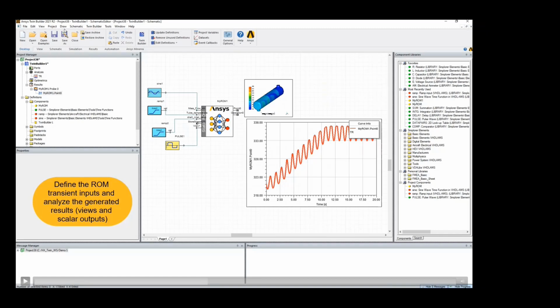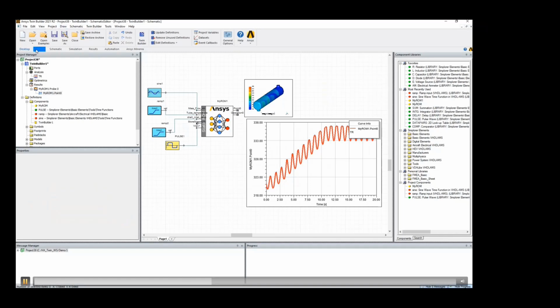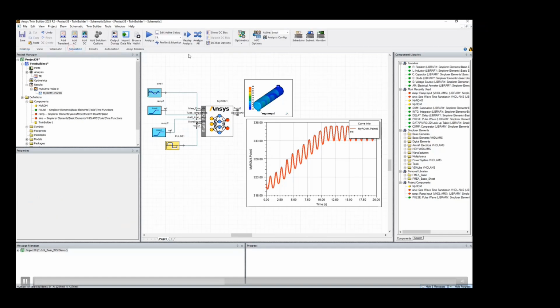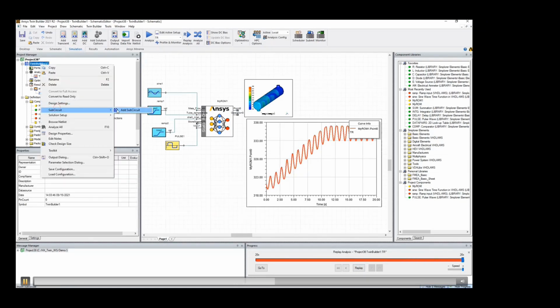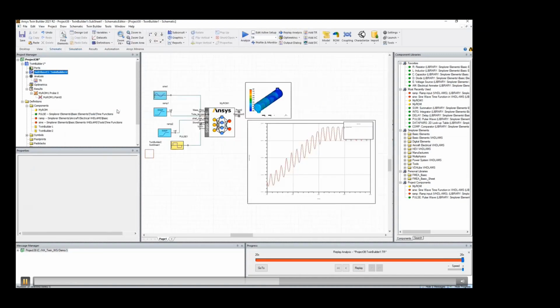And as soon as the reduced order model receives that sensor data, it's able to give you how the temperature distribution looks like inside the heat exchanger and what is the temperature at any physical point where I have created, how the temperature profile looks like at that point. So this data was not there previously, and this essentially is the virtual sensor. So this sensor is not present in my original case, but now I have this extra sensor data, which is coming from my simulation. So that's the virtual sensor.